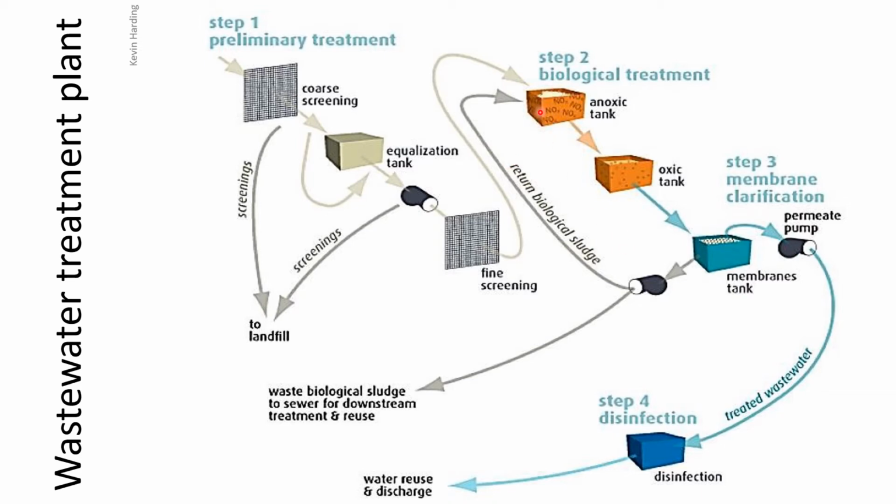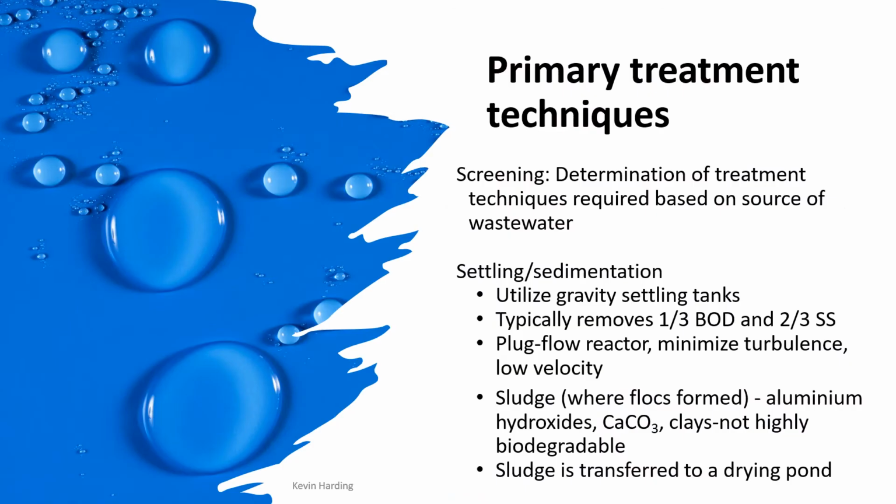So in these systems, these biological tanks, we have microorganisms in here that are going to be reacting with the water, with the sludge, to neutralize them, either in an aerobic or an anaerobic system. Those microorganisms we don't want to just send straight out into both the solid stream or into the water stream. Well, actually, the microorganisms we don't want in the water stream, we only want them in the solid stream. But because those organisms are now used to the systems and have grown acclimatized to what's going on here, some of them get sent back for a recycle. So those healthy microorganisms can get sent back and do their jobs. That's why there's this recycle happening here.